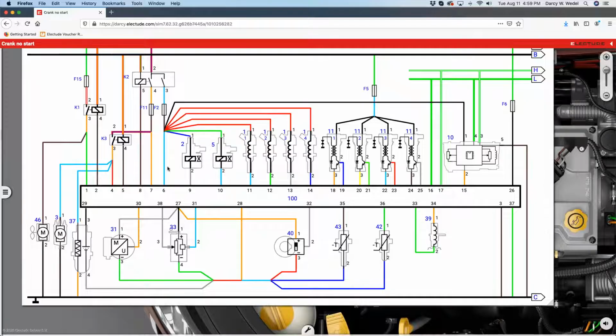There's an open, it'll set basically an open circuit for this fuse or this relay. So these are signal wires. Same thing here. There's a little resistor in the computer, and it's monitoring the voltage drop across that. If it doesn't see a voltage drop, then it knows that either this fuse or this relay isn't working. So these are signal wires, not power wires going into the ECU.